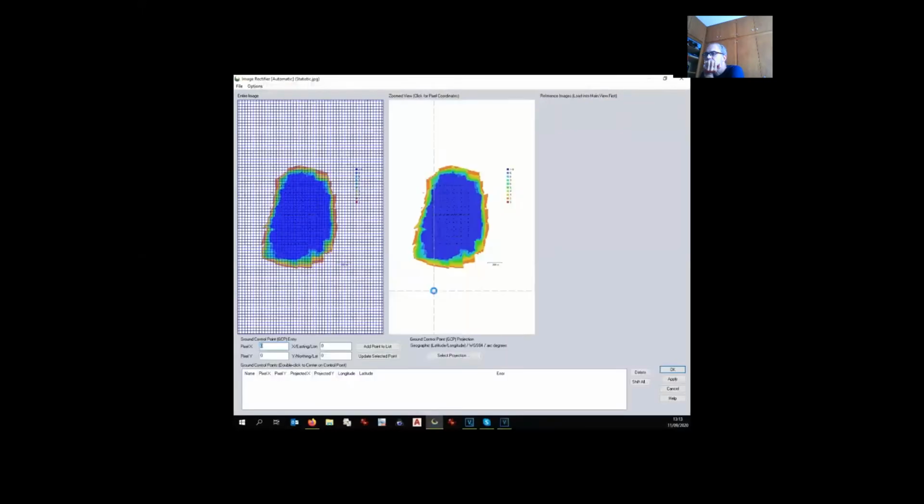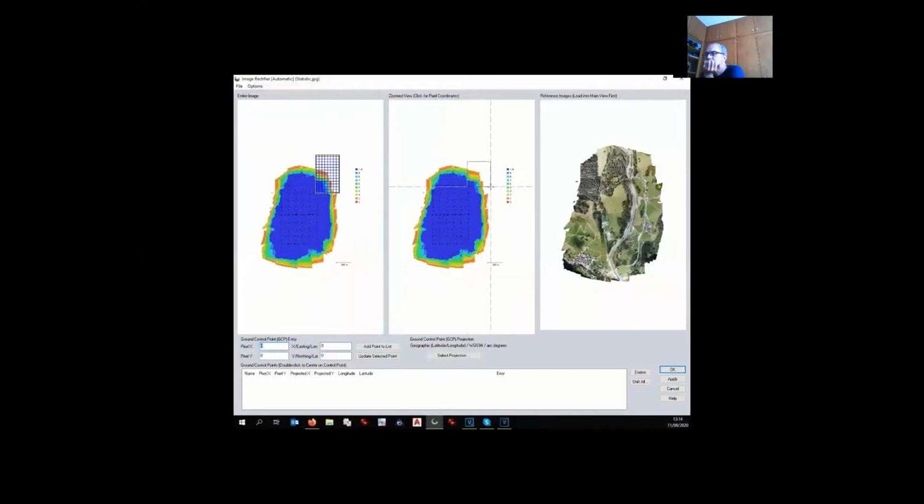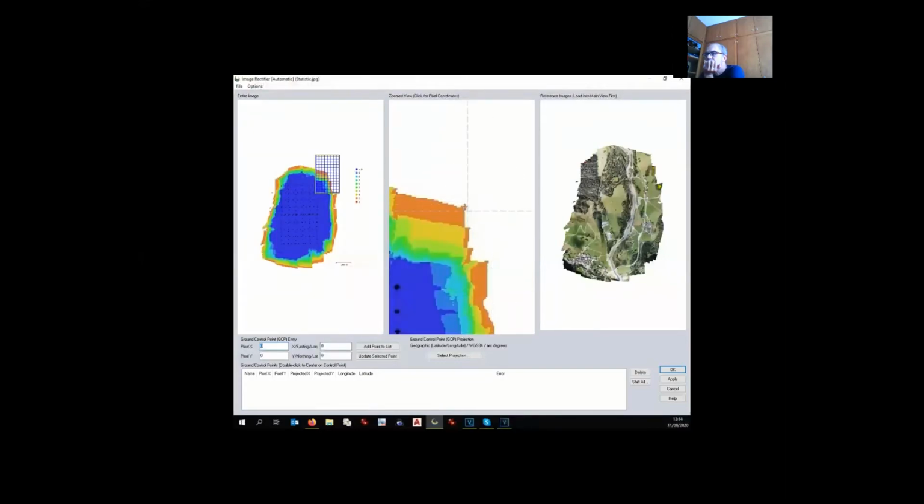This picture is not georeferenced, unfortunately. That's why we have to manually georeference the picture. It is a very easy task in Global Mapper. You need to find at least 3 reference points.